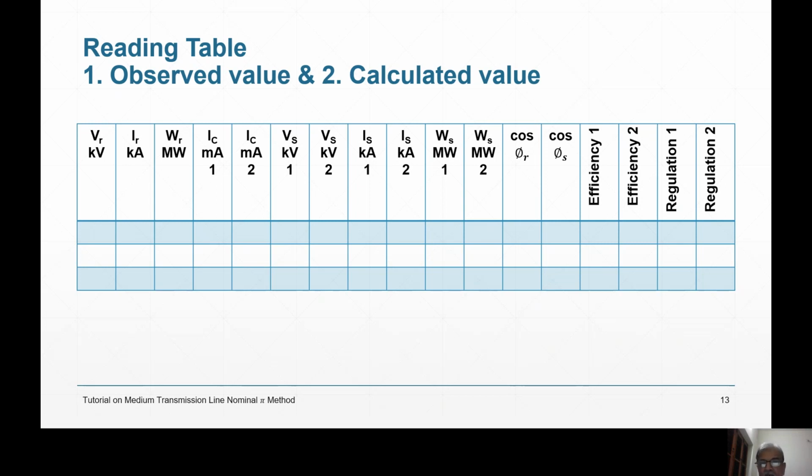And you have to see to it that at every load, the losses should be as small as possible. And for that, you will have to take action well in advance before erecting the line. Because efficiency is due to R, and R is due to the dimension of the wire. R is equal to rho L by A. L is not under your control because you want a 100 km long line, which means a long line. That is there, right?